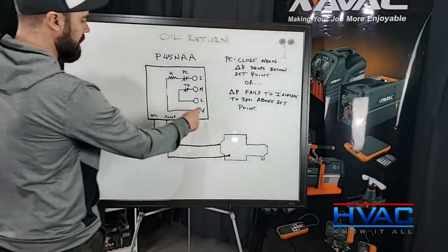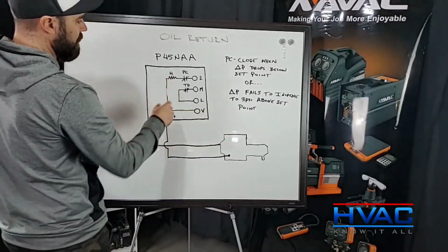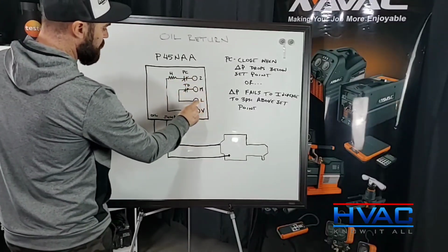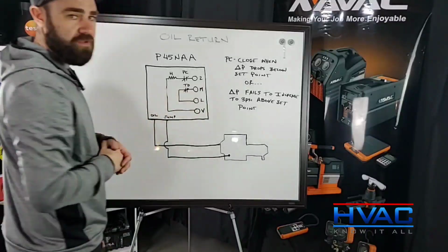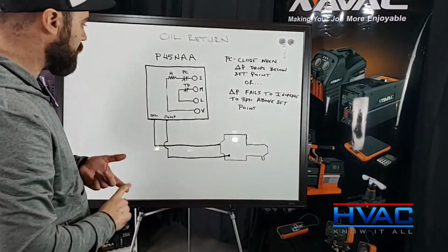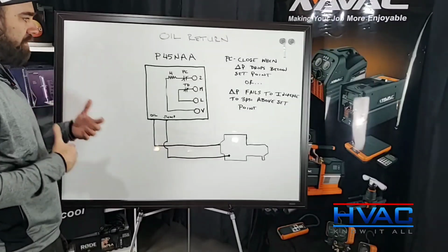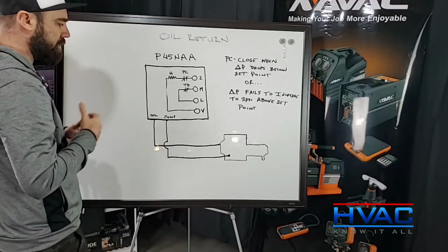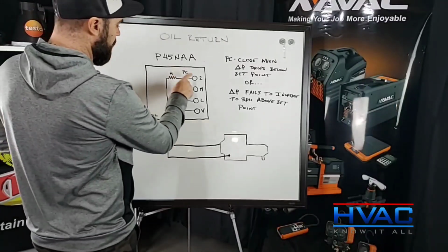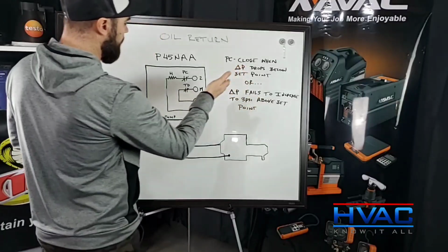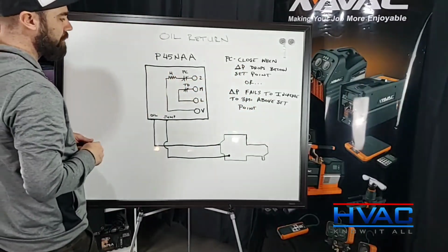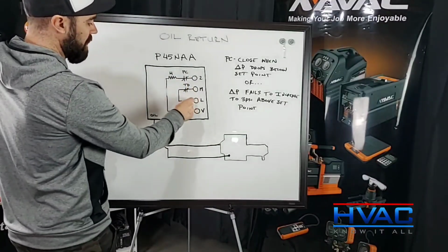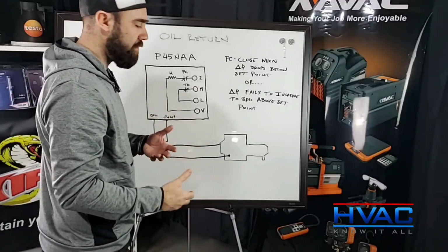We have a couple of circuits here. This one gets powered when the compressor contactor pulls in. Okay, and then we engage this heater. Okay, this one here is a control circuit tied in with the safeties like high pressure, low pressure, and so forth. Compressor starts. All right, we start to build pressure. If we build pressure 3 psi above set point before the time delay is over, heater is taken out of the circuit, time delay contact stays closed, and we continue to run.